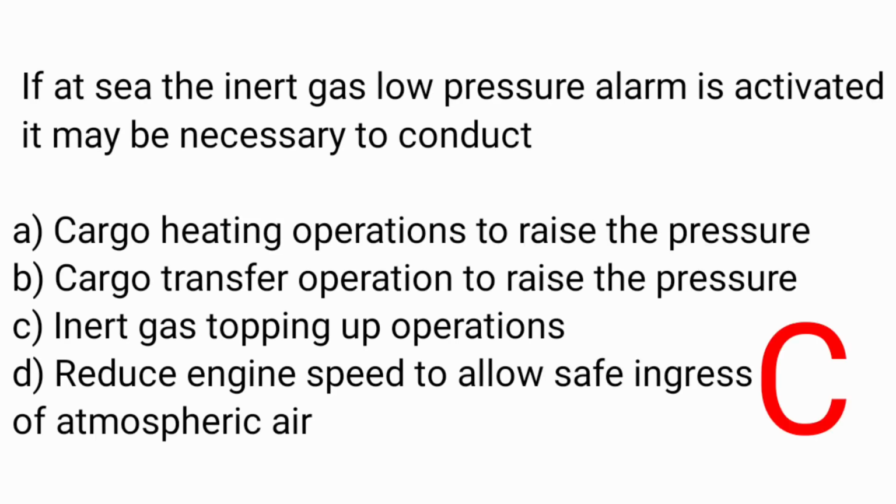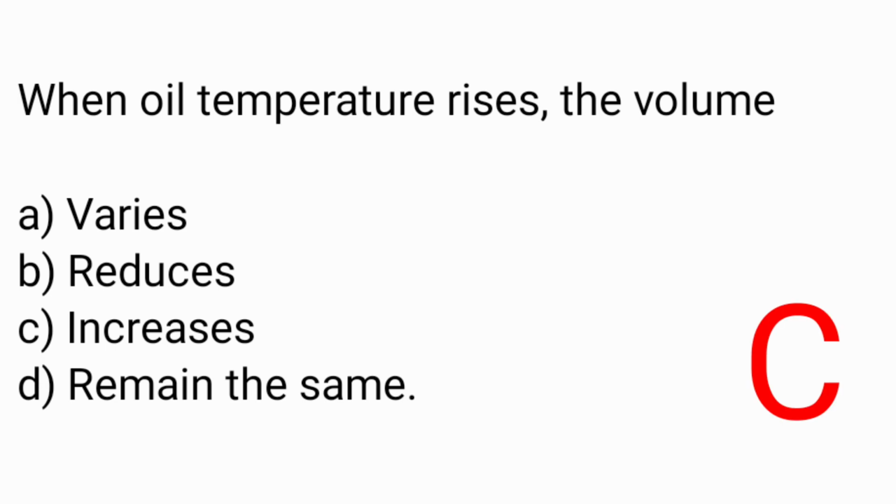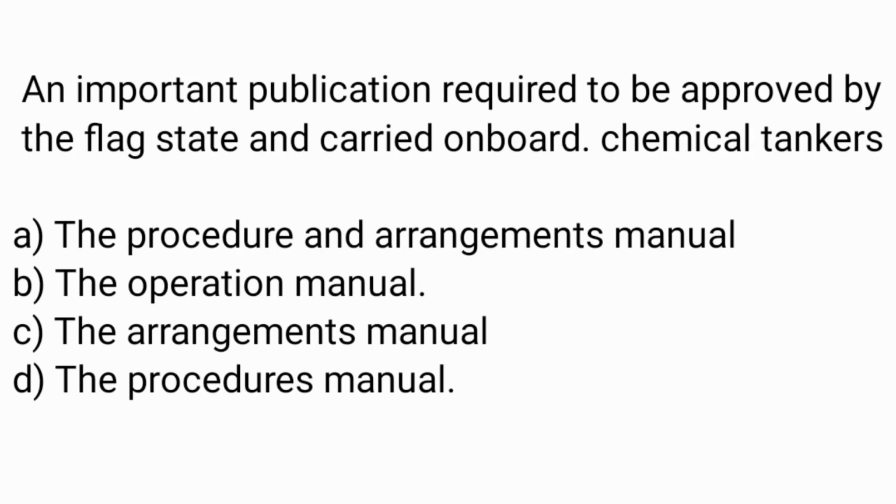If at sea the inert gas low pressure alarm is activated, it may be necessary to conduct. Answer C, inert gas topping up operations. As oil temperature rises, the volume. Answer C, increases. An important publication required to be approved by the flag state and carried on board chemical tankers. Answer A, the procedures and arrangements manual.